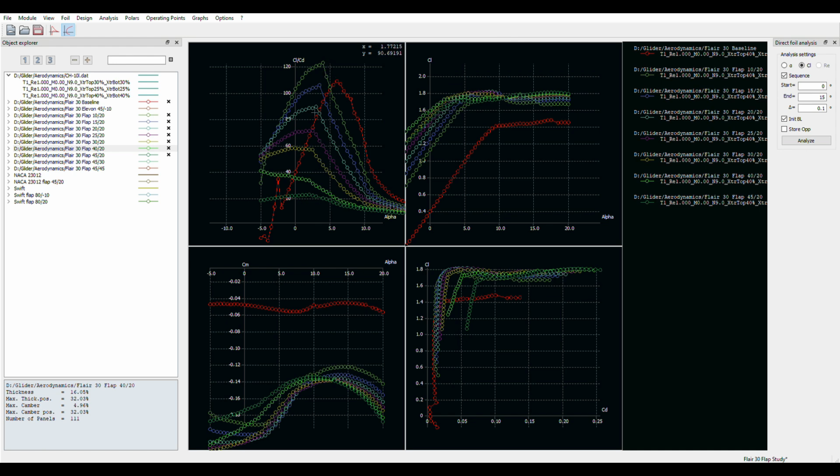Or it could have just been the fact that they all looked at it and went, hey, that's pretty cool. Great idea. Look, it folds up small. It's also the hinge line for the controls, and let's go build it. Because if you look at a wing and you look at the hinge line, it's not intuitively obvious that if I move the hinge line forward, I'm going to ruin the performance of my wing. That's not the first thing that pops into your head. And if you're an aero engineer, you wouldn't even think to put the hinge line at 50% because none of your professors have ever told you to do that.